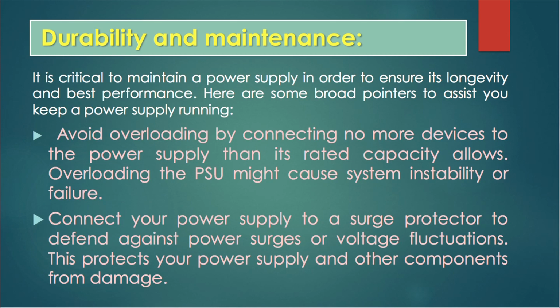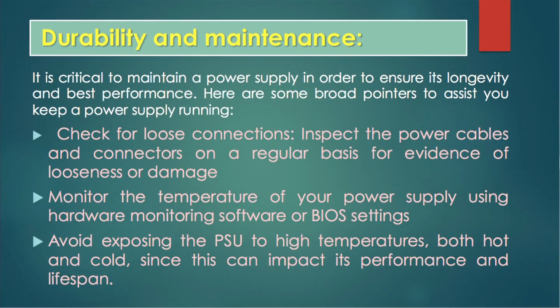Connect your power supply to a surge protector to defend against power surges or voltage fluctuation. And inspect the power cable and connections on a regular basis for evidence of looseness or damage. Maintain the temperature of your power supply using hardware monitoring software or BIOS settings. And the last point, avoid exposing the power supply to high temperature.